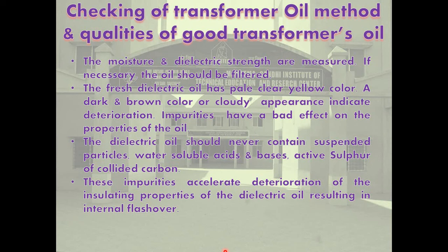Viscosity indicates fluidity. Oil with low viscosity has more fluidity and gives better cooling. At lower ambient temperature, the viscosity sharply rises and the speed of oil circulation reduces. Hence, viscosity should be measured at various temperatures and the characteristics should be plotted.